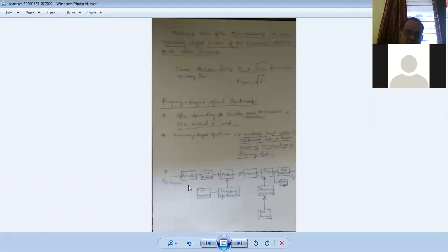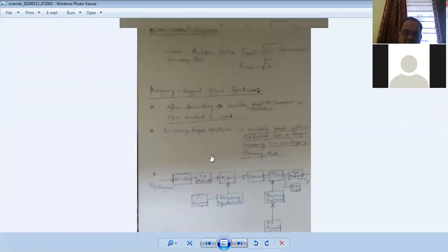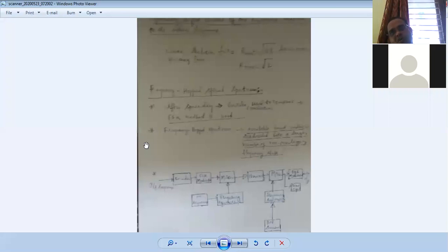Now how exactly does it work here? It is very simple. We utilize this for FSK modulation tactics. Once this is driven by the PN sequences, then different frequencies will be utilized and it will be transported in the same manner. Despreading takes place at the receiver. Here the channel information will be coded and goes to the FSK frequency shift modulator.